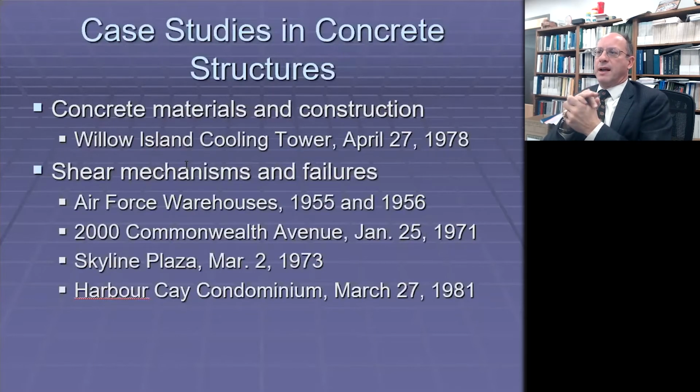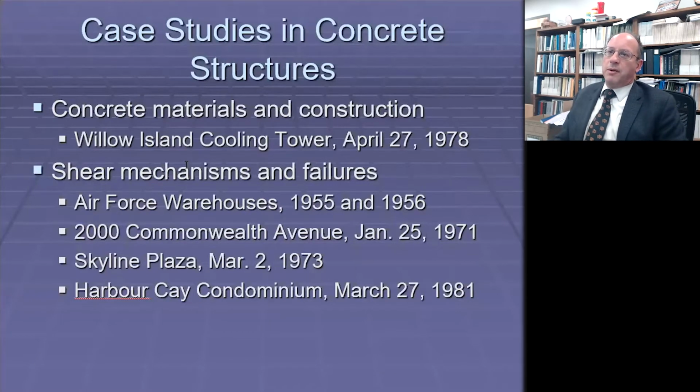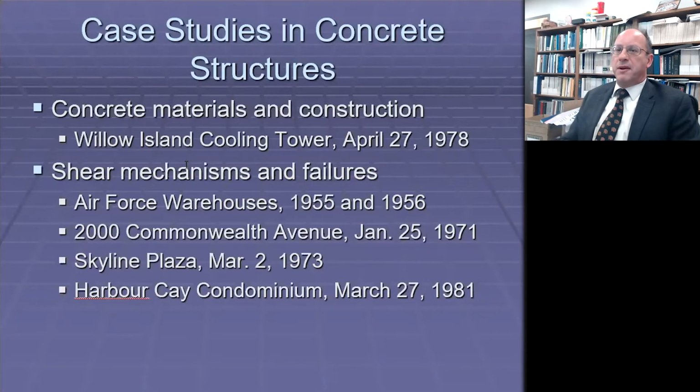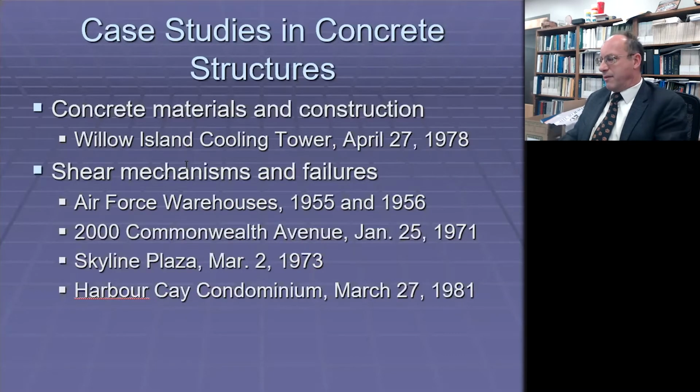Specific to concrete and concrete structures, there are a number of very important case studies. Willow Island Cooling Tower, which is really about formwork. The Air Force warehouse collapses of '55 and '56 that made their way into the codes in terms of shear reinforcement. And then a series over about 10 years of punching shear collapses of structures, starting with 2000 Commonwealth Avenue.